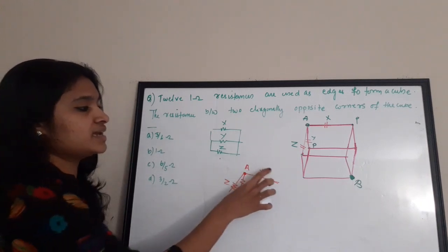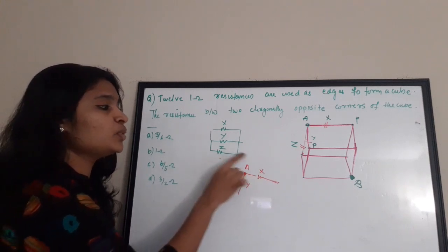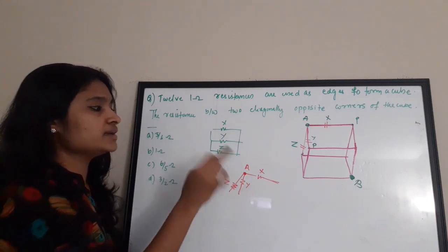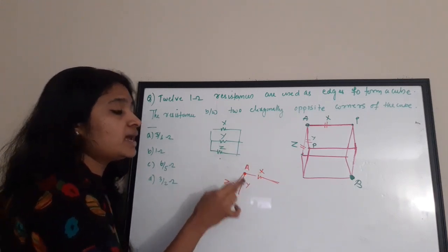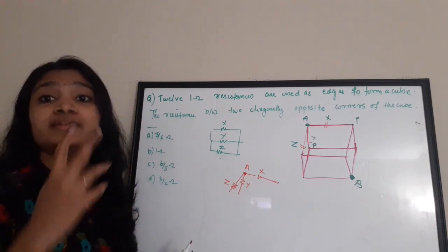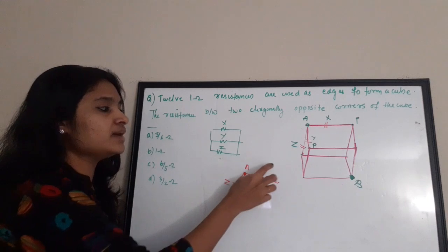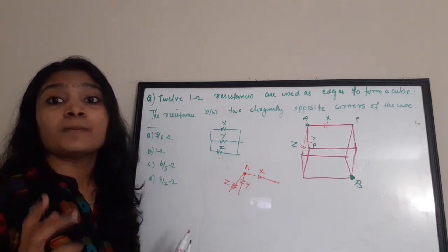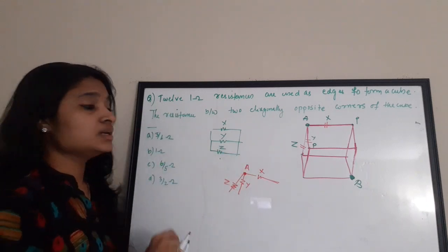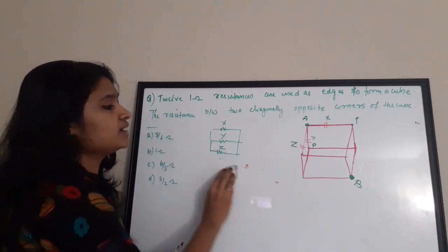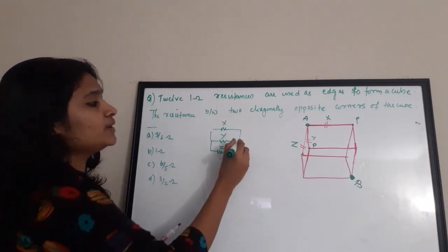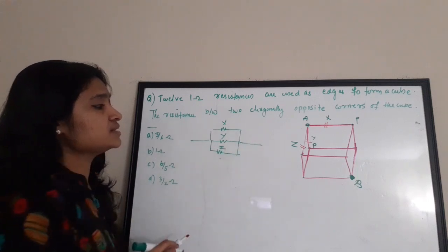Okay, so this X, Y and Z are connected at one point A, that is, the terminals of the X, Y and Z resistors are connected to one point A, and the other terminals are connected to three same-potential regions, and hence we can consider X, Y and Z to be in parallel connection. This is the theory of this cube formed by resistors. So we can consider X, Y and Z connected in parallel, right? So what will be the equivalent value of resistance here?